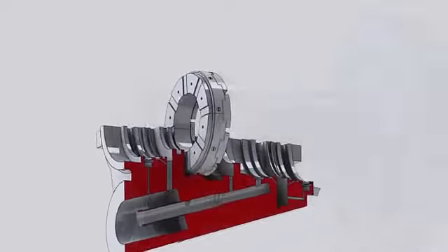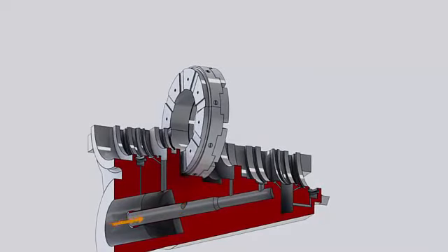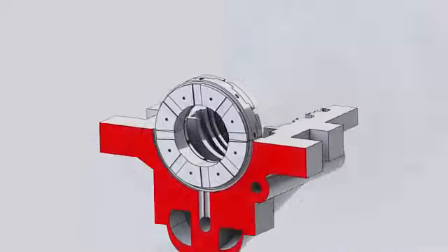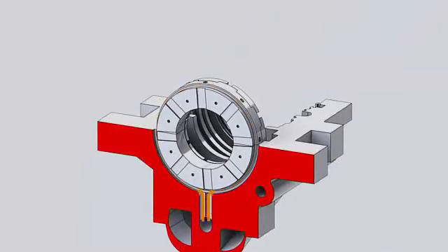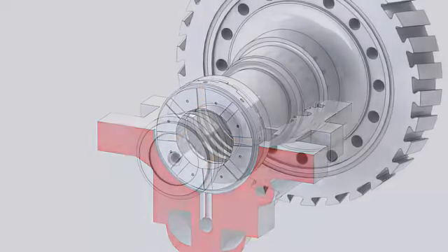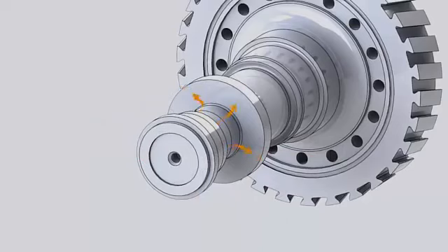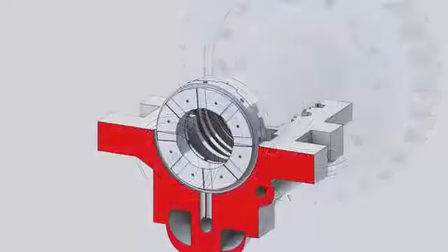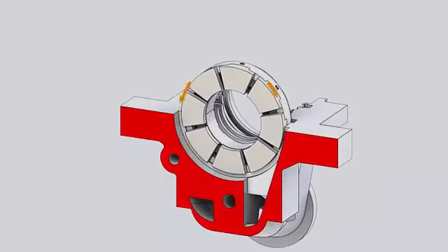For lubrication, oil is supplied through the oil feed pipe to two ports in the lower bearing housing, where the oil flows into annular space around the base ring. Then, oil flows through grooves machined on the back side of the base ring to the bearing cavity, where it is carried by the pumping action of the thrust runner to the entire bearing surfaces. Oil exits at the pad's periphery to the thrust bearing drain cavity down to the lube oil drain piping.